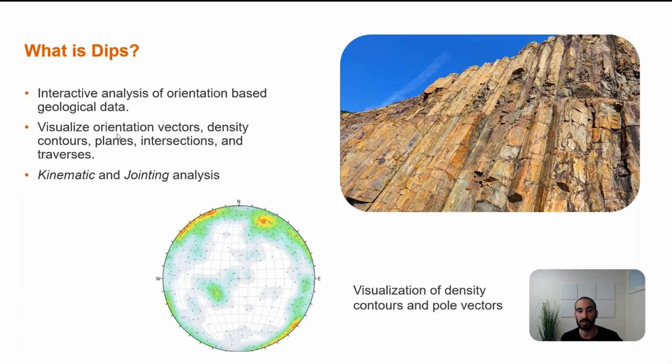And DIPS also allows users to perform true and apparent spacing in joint set, rock quality designation analysis, RQD, and frequency analysis on the field data. Additionally, you can view the strike density, frequency of your measured data using the rosette plot, which is included in DIPS. You can also draw user-defined planes, sets, and include annotated tools for your reporting purposes.